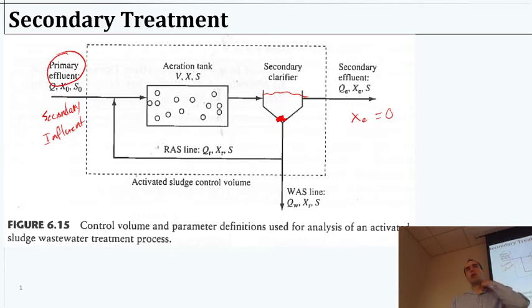the role of controlling the waste activated sludge line. So WAS, it's a waste activated sludge. That's really important because that's how much sludge we're sending to the landfill. That's going to control, if we waste more, then we're recycling less, because we're going to be accumulating some set amount in our clarifier. So if we are sending most of that to solid waste, that means we're not recycling much.